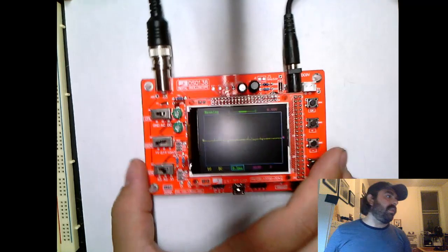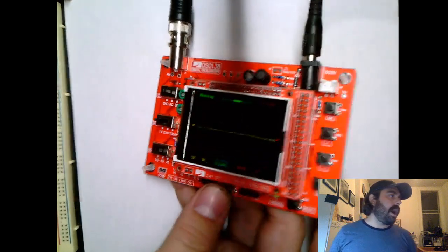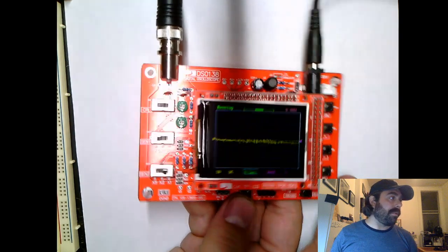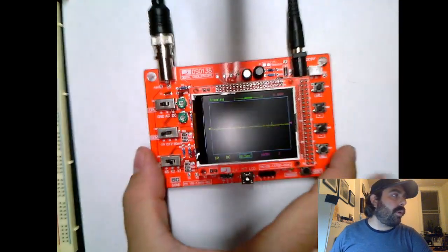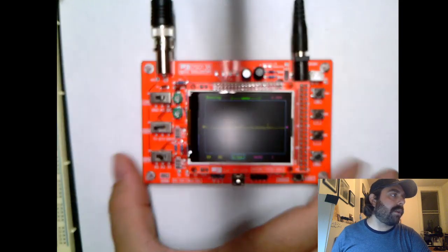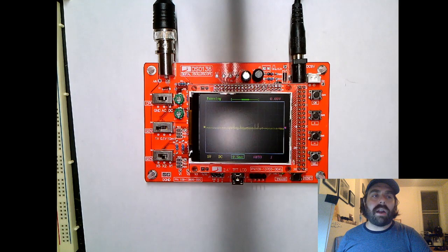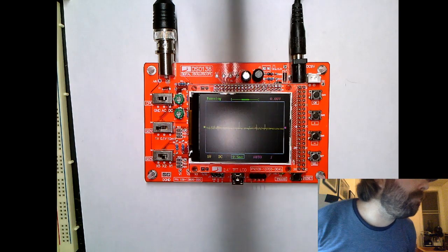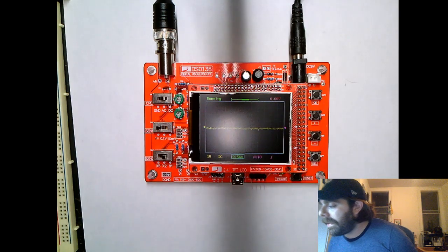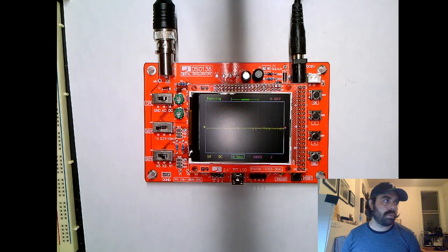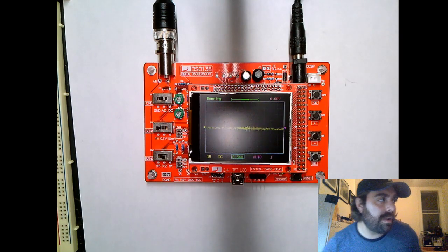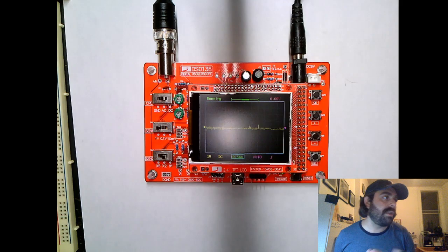First, let's talk about this oscilloscope. This model was one that I was able to find on Amazon for a relatively cheap price, one that we could use in this class. The oscilloscopes at the NYU lab are several thousands of dollars, and this was the one area that was the most difficult for me to figure out how to adapt to doing this at home. The first thing you should know is that an oscilloscope is a way we can visualize waveforms. Today we're going to look at some sine waves and square waves, and use the oscilloscope to see how to read them.